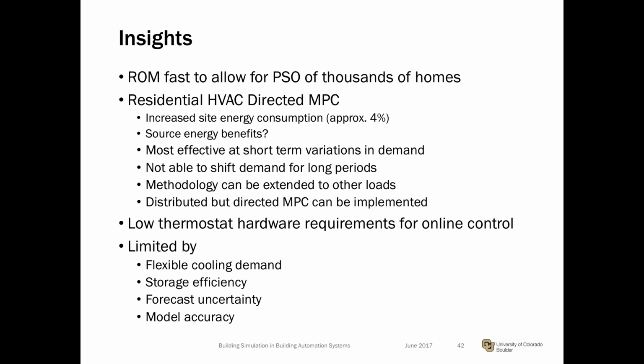But given the building construction in the US, we are recognizing that we have limitations in terms of the cooling demand that we can actually modify. There's only a limited flexible cooling demand. The timber frame construction has limited storage efficiency, and in any real-time MPC case, we're struggling with forecasting uncertainty and model accuracy issues.